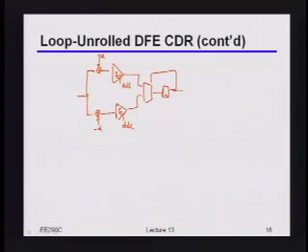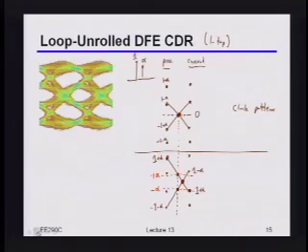Okay, but now what we're basically saying is that if we want to do clock recovery for this thing as well, then if we really want to, again, use every single one of those edges and make sure that it has the best possible timing information, then now notice we actually need 3 different thresholds. We need one at 0, we need one at plus alpha, and one at minus alpha.